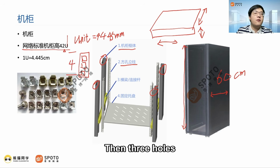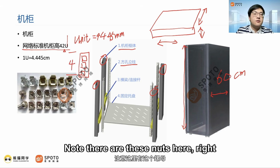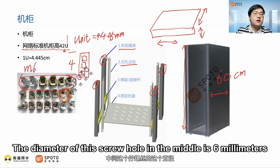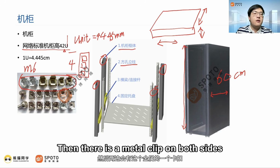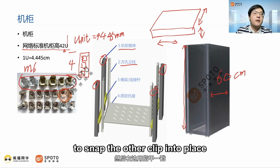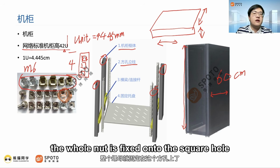Then 3 holes. How do we install this device? Note there are these nuts here. These nuts are M6, that is, the diameter of this screw hole in the middle is 6 millimeters. Then there is a metal clip on both sides. You press the clip on the left side, and then push with your fingernail on the right to snap the other clip into place. In this way, the whole nut is fixed onto the square hole.